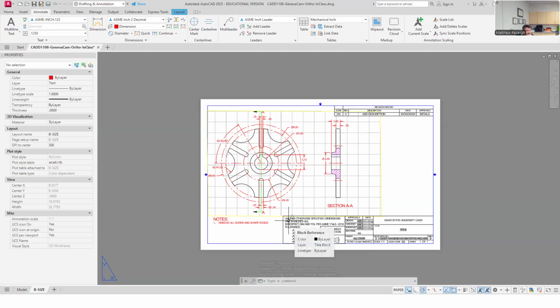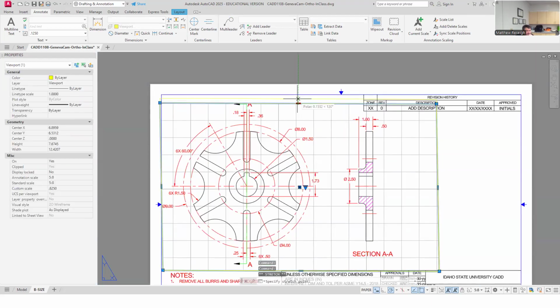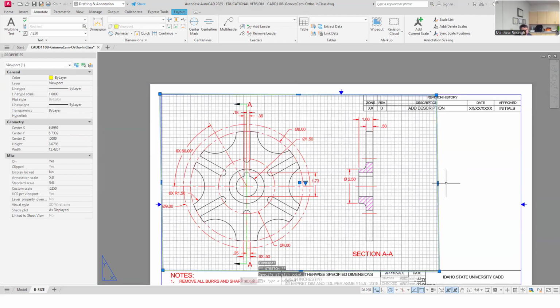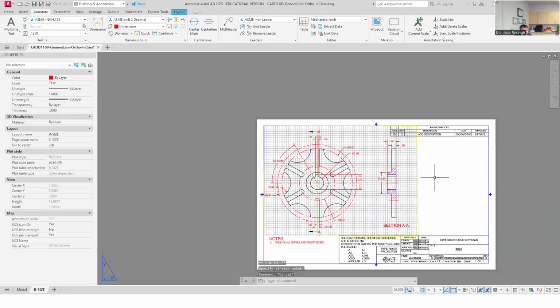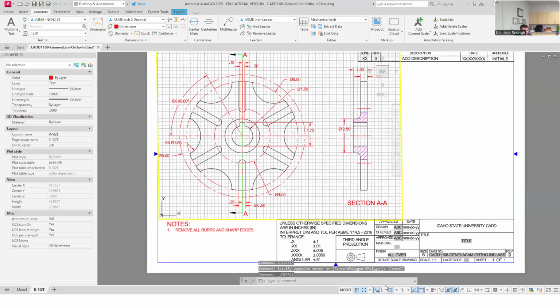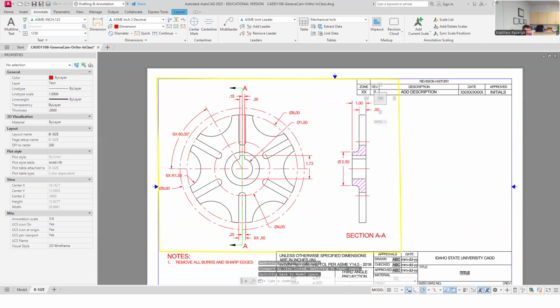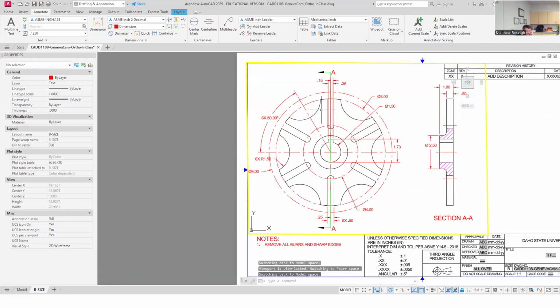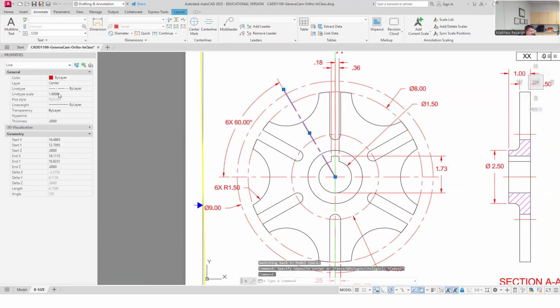It's a good thing I didn't do 3/4. 5/8 is a good scale. I can just adjust this up a little bit and that'll show my. I think that looks really good. Take a look here. Turn off that snap trigger. Now I can look at my line type scales and decide what I want to change those to. So I'm back in here now. My line type scales. It's hard for me to see it through the grid a little bit. My old eyes.